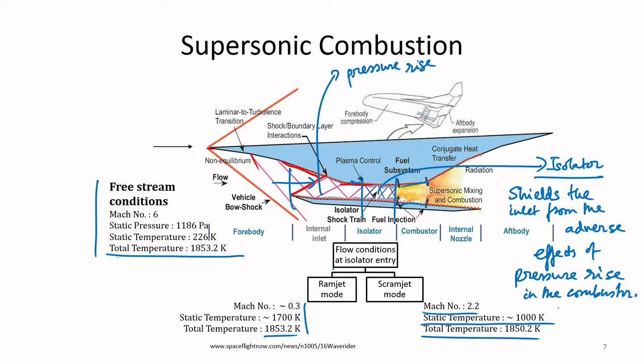So you see why this scramjet mode of operation is preferred: the static temperature of the flow that enters into the combustor is at much lower temperature, and there is room to add heat into the flow without inducing strong dissociation reactions. You can add heat into 1000 Kelvin and take it to say 2200 Kelvin. But what will you do at adding heat into this flow? There is nothing.